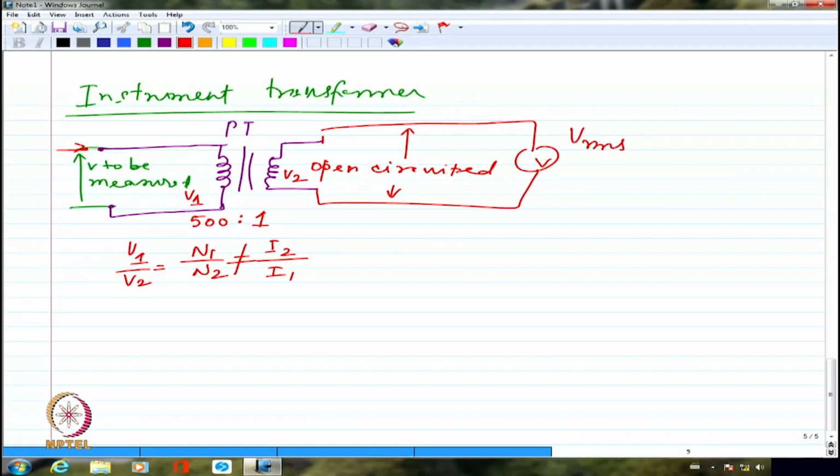That is where the per unit system is very useful. If I say this potential transformer is going to be of 1 volt ampere rating, and it is going to be 500 kilovolts divided by 1 kilovolt, then I can definitely calculate what the base impedances are. Compared to the base impedance, the voltmeter impedance has to be quite higher. Then I am fine.